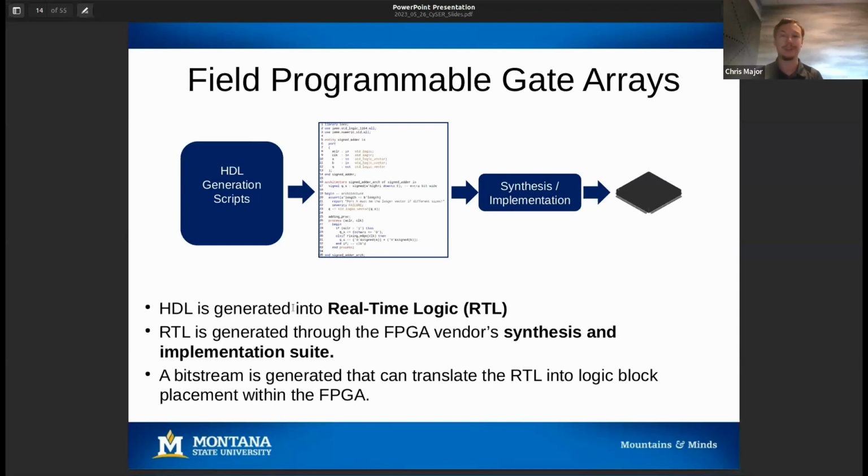So basically, imagine your compiler software provided by Intel Altera, AMD Xilinx, Lattice, etc., one of those companies. They hand you the software package and they say, hey, just throw in your HDL. We got a couple of custom scripts for you. We'll go ahead and we'll handle the process of putting it on the FPGA. And as an end result of that process, you now have a bit stream. So we take our custom hardware on the bit stream and we throw it onto an FPGA.